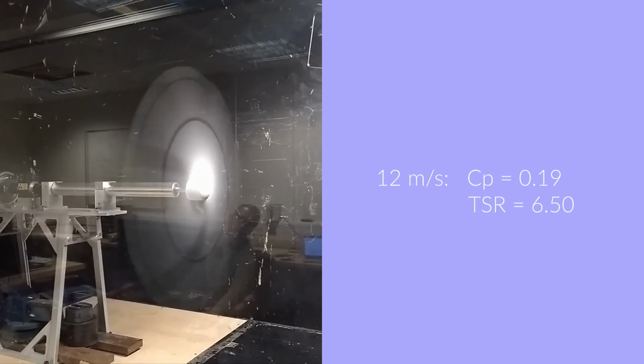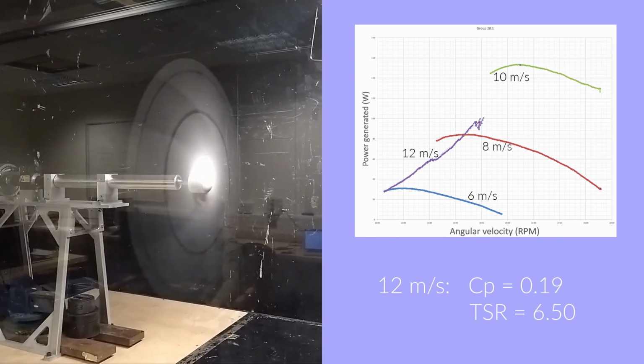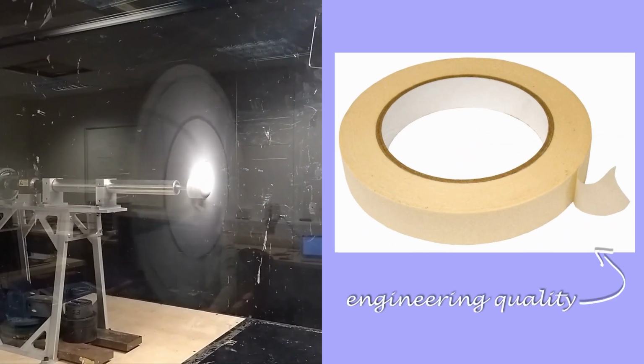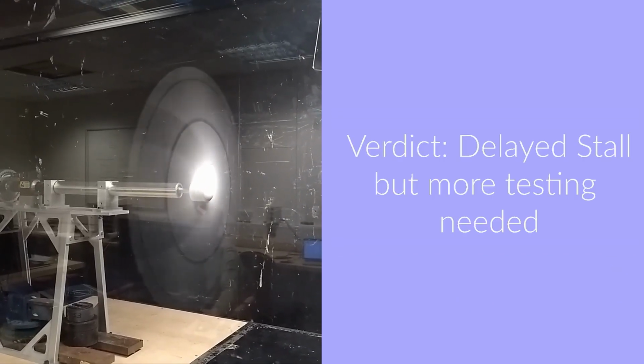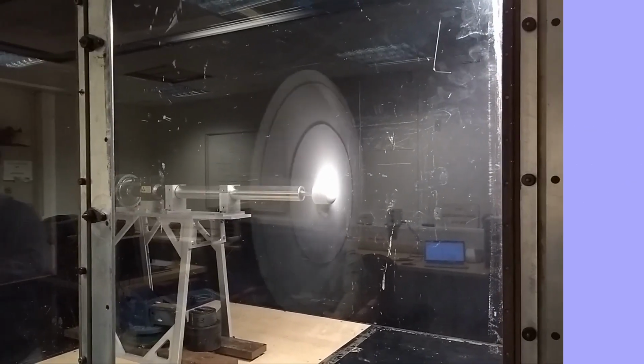At 12 meters per second, the blade was completely stalled, as shown by the low power CP and the power curve. By covering up the vortex generator jets with a piece of tape, we are able to qualitatively evaluate their performance. We concluded that they did improve the off-design performance of the blade by delaying the catastrophic stall when they were open and working.